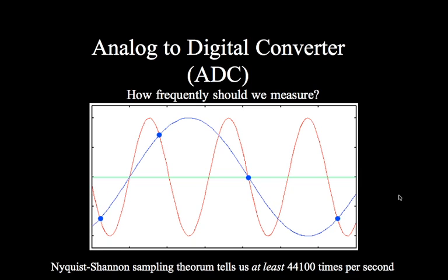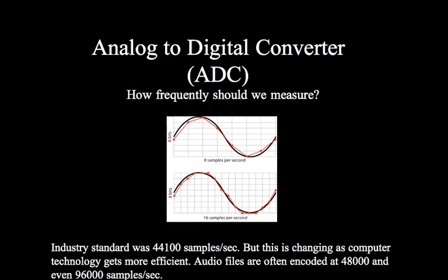There's all these weird sounds in there that were not in there before. But we don't hear those because all those digital artifacts should be well outside of our range of hearing. Okay, so this led to the Shannon Nyquist number, 44,100 samples per second. The reason it's that is it's double the range of human hearing, and the idea is that means that all the digital artifacts will happen outside of what we can hear.